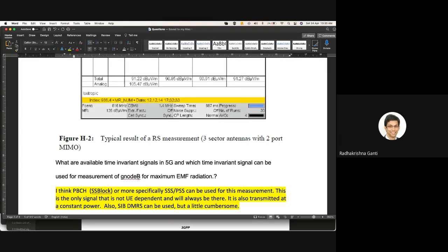Then in 5G, they made this call that for power saving, you should be able to shut down a large portion of the base station, except where you transmit the synchronization block. The synchronization block is just 1.2 megahertz now. So you just transmit those 1.2 megahertz. And once a UE gets locked, that particular part where it's serving can be on. That is the reason why there are no common cell reference signals in 5G, mainly for power saving for the base station.